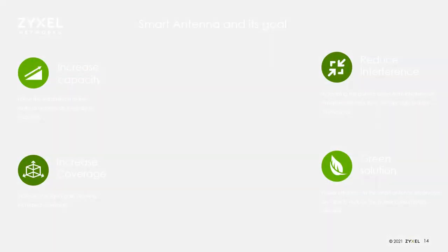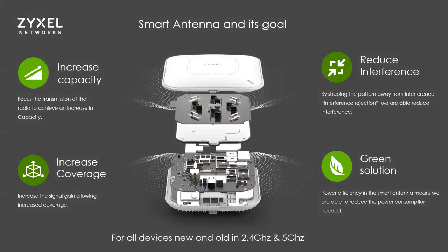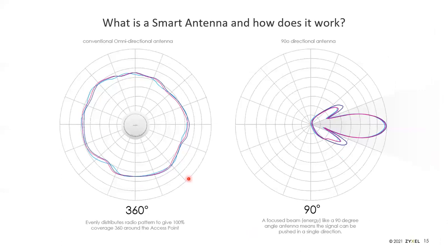So our smart antenna technology that we use is specifically optimized to be able to increase the number of devices that can use the same access point before you experience any sort of issues with your wireless network. It's designed to reduce interference between access points, increases the range or the amount of area that can be covered, and also has the ability to drop down the amount of power utilization. So again, here's your typical, standard ceiling mount antenna. It's got a nice round pattern. Over here, we've got a wall mount directional antenna, something you would generally use in an outdoor environment. But in both cases, they've essentially got a fixed coverage area that they provide coverage to and where the signal is getting out to.